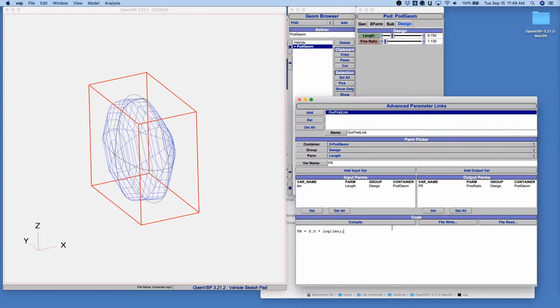And so then you can have something like, if you need to be able to identify a video target from a 12-mile slant range in infrared, and you're going on KU band satellite, you could have links set up to size both the optics of your sensor as well as the size of the dish, all based on what's your slant range and what's your requirement for your sensor.